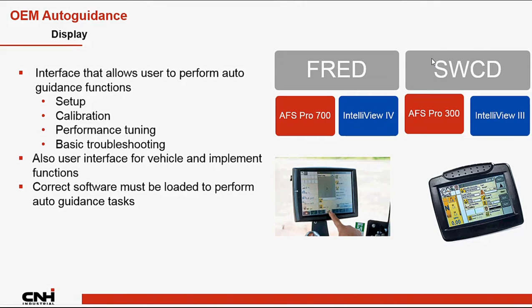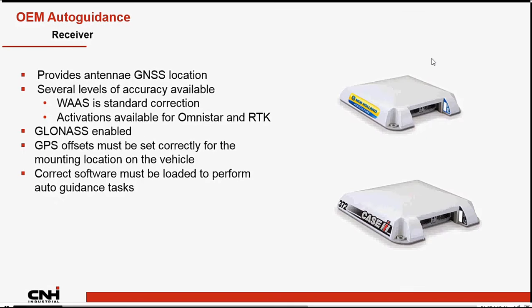And on the bottom of the screen you'll see you need the correct software must be loaded to perform auto guidance tasks. And you need to make sure all of your components are up to date with the same software so they will all communicate together effectively.